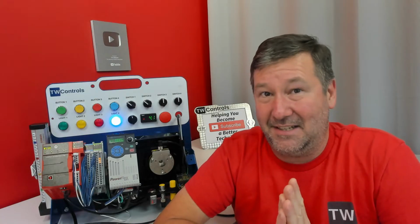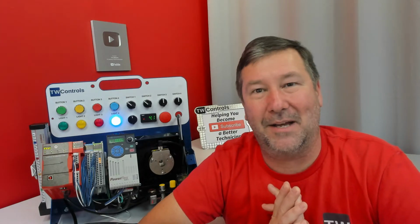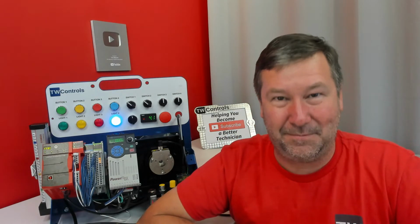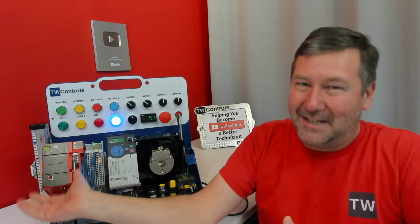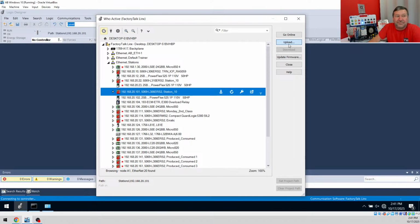PLCs are the opposite of the internet. And I hear a lot of things about how to remember it. Actually, I had somebody like 4 months ago finally say something. I'm like, wow, why have I never thought of that one? But download equals downtime. Upload equals uptime. Because yes, if you accidentally download to the wrong PLC, or you accidentally download when you think you're uploading, you're going to take that PLC down. And if you want to pull the program out of it, it is upload. So we're going to go upload.